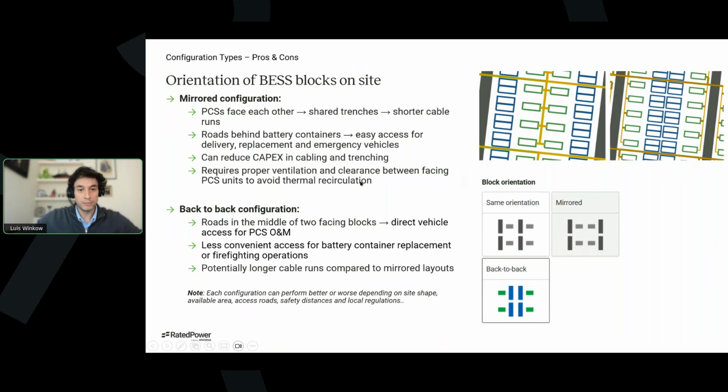And yeah, you also have to consider, as our PCS are facing each other, proper ventilation and clearance between facing PCS units to avoid thermal recirculation. So we will see we also have distances that you can define between the different PCS, having this in mind.